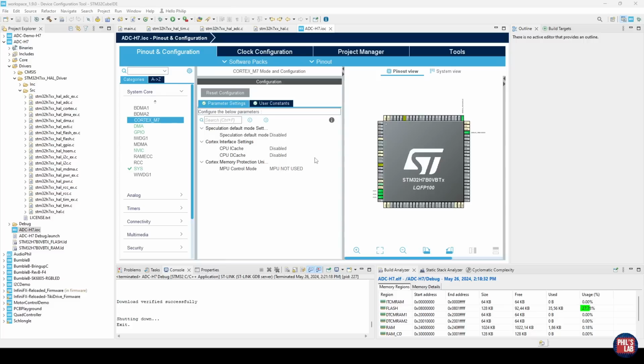The problem is with the cache, you have to do extra cache control when using DMAs. One way to get around that, for example, if you have low speed requirements, such as in this case where the ADC is just used for control settings, and we don't actually need the speeds of these caches, but we do want them enabled, for example, for other segments in our design, what we can do is place the DMA